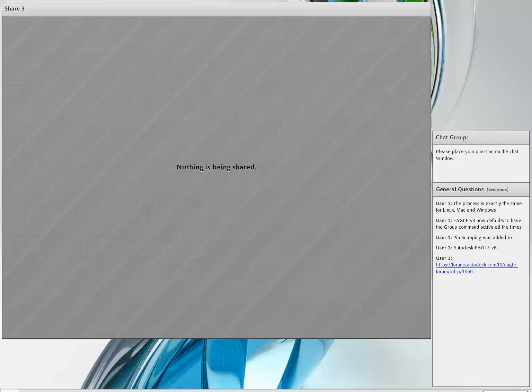Also, we went through those last steps that usually are very essential when you're working on a schematic, or almost done with your schematic, which is to create a list of the parts you're going to be needing, also referred to as the bill of materials. The bill of materials will give you that list. You could export it in multiple formats in Eagle. Also, if you wish to add attributes to your components in the schematic editor, those attributes you define will also be placed on the bill of materials.